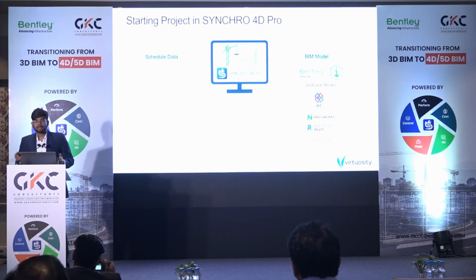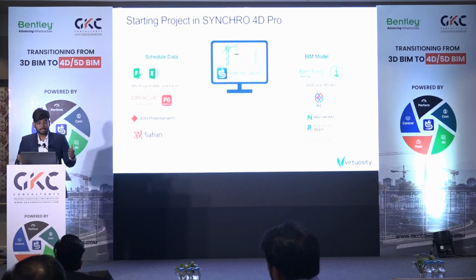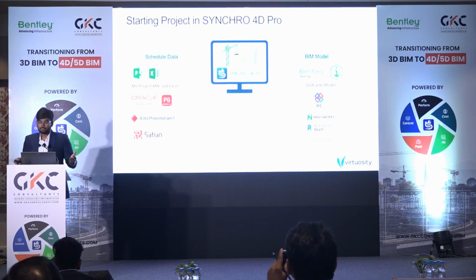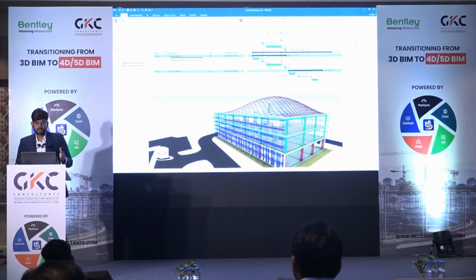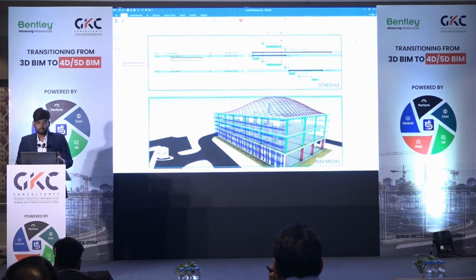Or maybe we can quickly create an outline or lower level schedule in any of the following conventional planning tools like P6, MSP, Asta Powerproject, Safran, and take them inside Synchro. When we take them inside, this is where we start the journey of 4D. You see in the top there is your schedule, and in the bottom you see your BIM model.